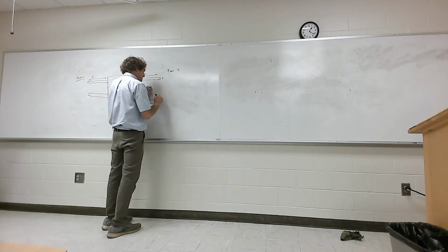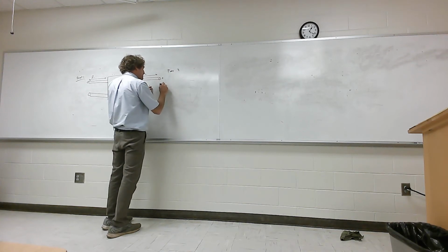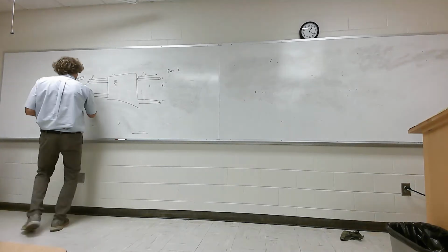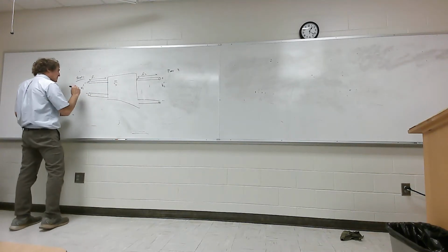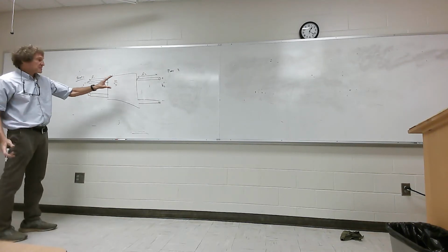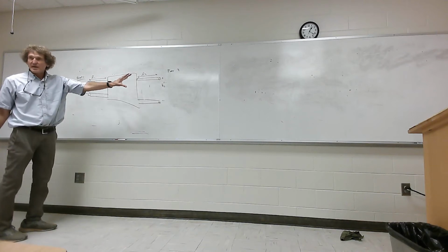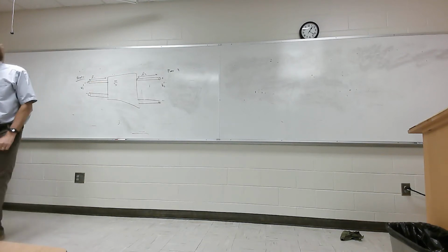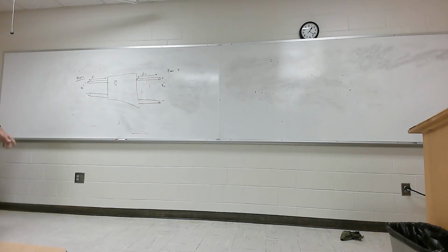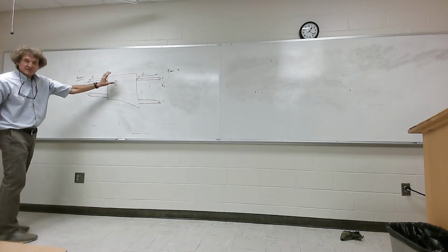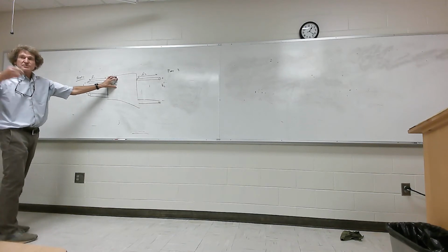So here's where my measurement's going to be. This is going to be my V2 prime. This is going to be my V1 prime. But I've had a device, and now I add these links to it. The reason this is important is that when you're dealing with an S parameter measurement of something, if you want the S parameters of this matrix, you have to use cables to attach to it.